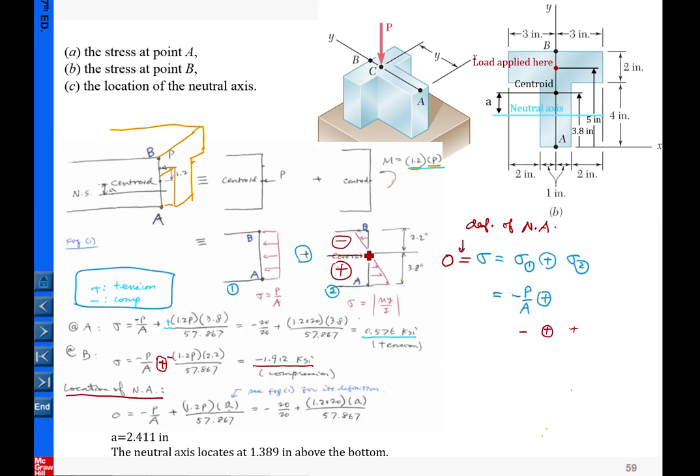So basically, before we proceed, you should be able to identify that the neutral axis should be located in the lower portion of the original system, because the negative and positive together will likely make 0 here. Okay. So now for this case, let me pick one here. So this is the location, and then the distance here, let me call it y, where the neutral axis is.